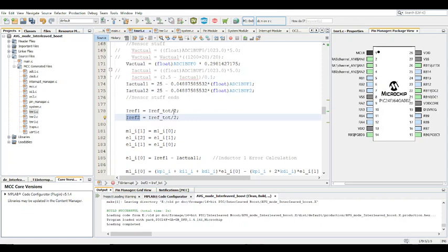Obviously, because it's one boost. Now there's two of them essentially in parallel, in a weird kind of way, in parallel to one another. So you sort of have to share the current. The current gets shared between the two inductors, which is a big advantage of interleaved topologies. It's shared current through the inductors, so the amount of stress is shared between two inductors, two diodes, two MOSFETs, and the capacitor just gets everything in the end, your output.